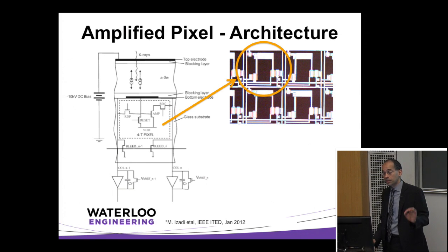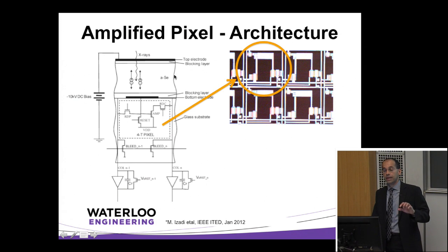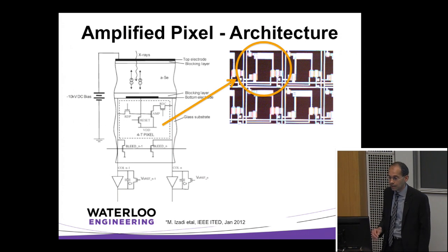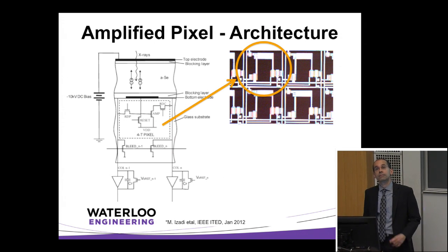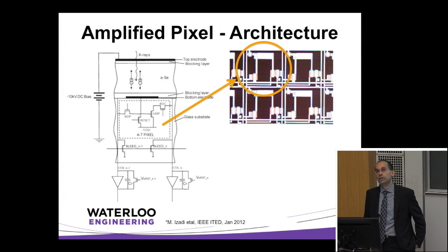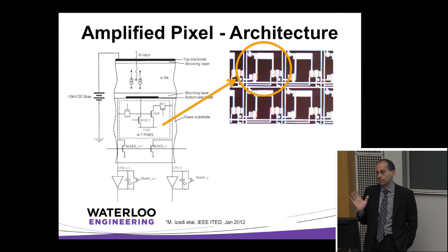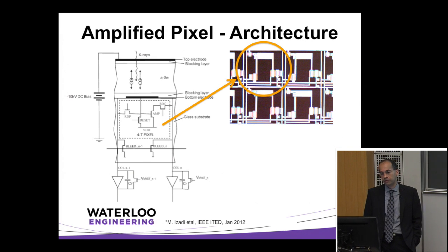And it had, most importantly, the selenium layer is very thick. It's like 1 millimeter thick. So the capacitance is tiny. You can control the capacitance to whatever you want, so you can get good gain. So we said, OK, why don't we build some devices using selenium? So this was work that we ran probably between 2005 and 2009. It was about a 4 or 5 year effort.